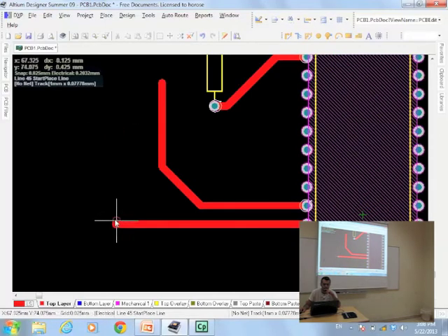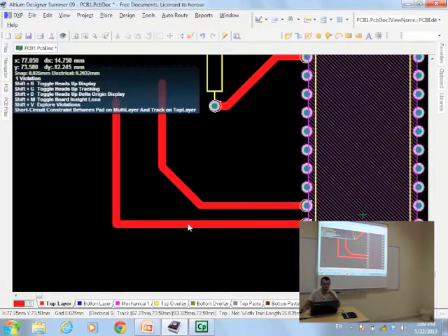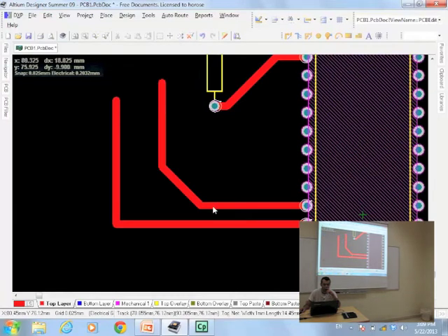If I do such a thing that it is 90 degrees, the signal comes here in higher frequencies, it hits this one and reflects back. Some of the power reflects back through the same track. So this is not working. This one, when it hits there, goes the other way. So this is one of the problems.